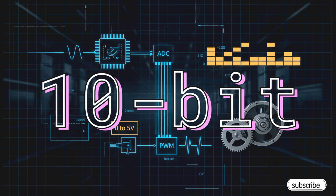And this brings us to a really key system parameter, resolution. The ADC in this microcontroller has a 10-bit resolution. So what does that actually mean? It means our entire 0 to 5 volt input range gets broken down, or quantized, into 1024 distinct steps, from 0 to 1023. This number is a huge deal because it directly dictates the precision of the entire control system. The higher the resolution, the finer the control we can achieve.